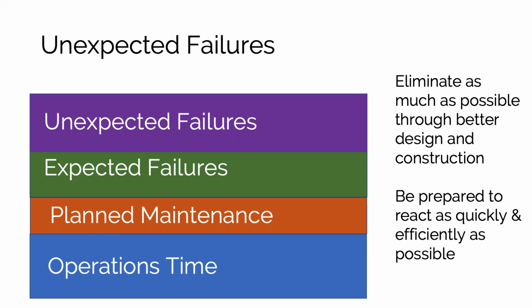And at first they didn't know why it happened. The motor just stopped. After it happened a few more times, they finally figured out that the juices from the cutie oranges were getting on the motor and causing the failure. The motor had been put in a place that wasn't good for the cutie operation, kind of below the conveyor belt, and it should have been put above. So they redesigned it to move the motor above the conveyor belt and stopped that kind of unexpected failure.